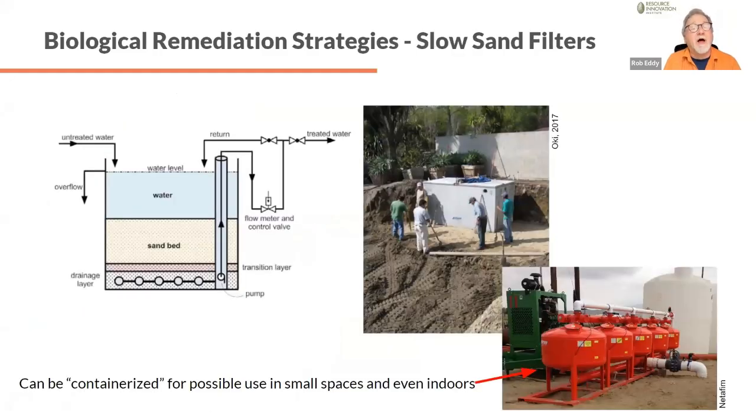Slow sand filters, where the water is allowed to filtrate through a sand bed. What ends up happening is the sand bed on its own forms this kind of layer of different kinds of organisms. It's got a special name, which I can't pronounce, but it's like algae and bacteria and such, which actually help tie up some of the contaminants. It's not just filtering. There's a whole symbiotic system going on of removing contaminants. Now, what's cool about this is it can be done outdoors.